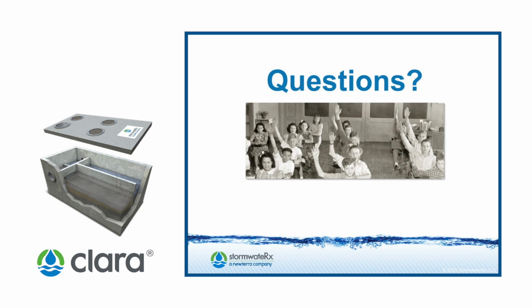And so it does require some occasional inspections just to make sure that it's processing the water that it's supposed to. So there should be some wet weather inspections occasionally, as well as some dry weather occasions when you can actually inspect the media itself to gauge the solids loading. We have an operation and maintenance manual that details those procedures. So it should be fairly simple, but it does require just occasional inspections.